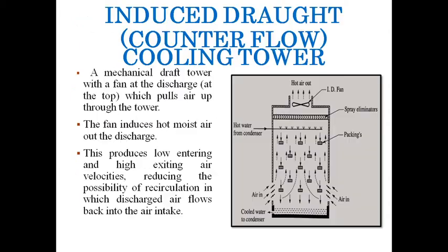Okay. Next one, induced draft counterflow cooling tower. This is also called mechanical draft cooling tower. Why? Because mechanical devices or external devices are used in this tower. What are the external devices? Fan or blower. This tower is also called counterflow cooling tower. Why? Because the flow directions are opposite. Are you clear or not?